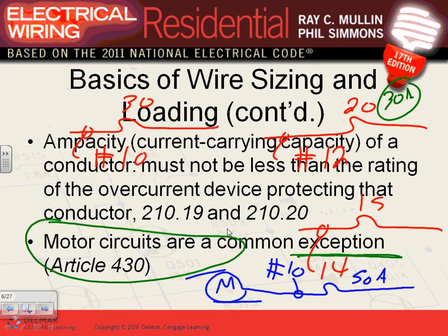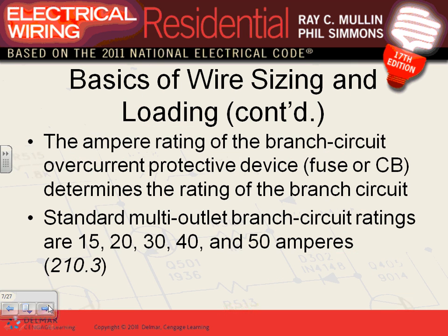Later on, when you go with me, we start talking about short circuit rating of the conductor. Right now, it's just overloading the conductor. Good example, the rating of the circuit. This is the most common mistake, guys. The rating of the circuit breaker is the rating of the circuit. So when I say a 100 amp branch circuit, this means the overcurrent device ahead of it is 100 amp. Does it mean the conductor is a certain size? No. The rating of the branch circuit is the rating of the overcurrent protection device. Example, let me tell you, here are 1, 2, 3, 4 branch circuits.